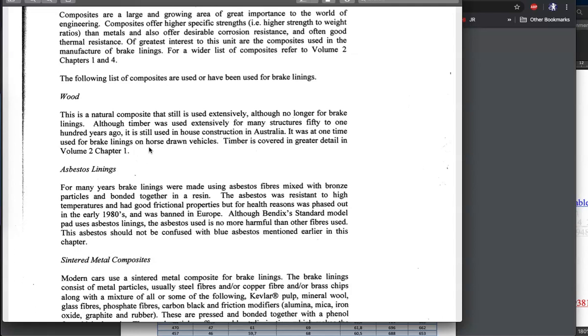So what you have to do instead is use smaller pieces of weaker timber, and they're stronger because of the glue. So we can have LVL, which is made of thin veneers, like plywood but a beam, or we could have glulam, which is just wooden beams glued together. They also are less likely to have defects, so that makes them stronger. They can be designed for any length and any shape. Compared to steel, they're easier to cut and join.